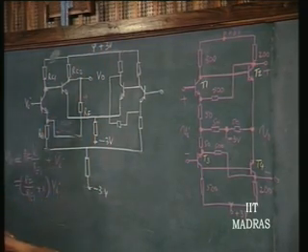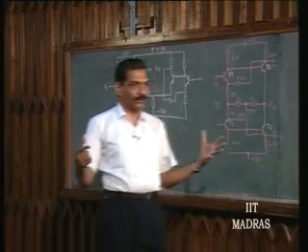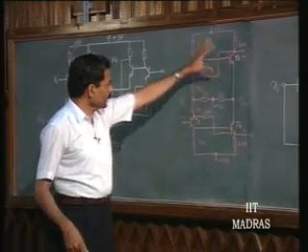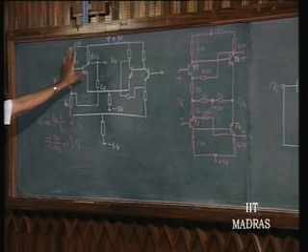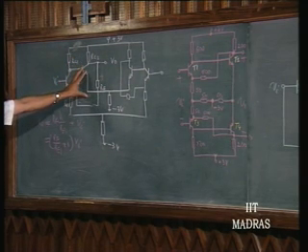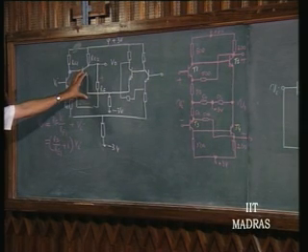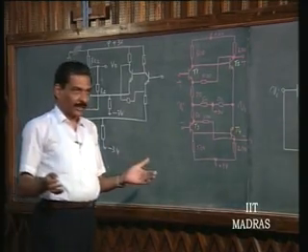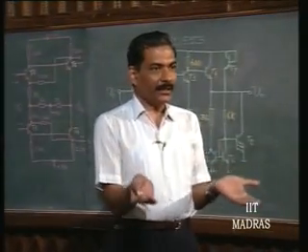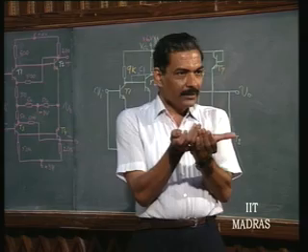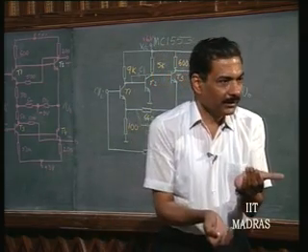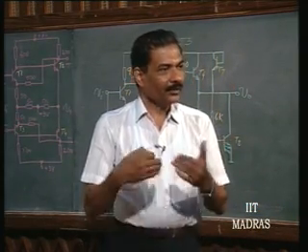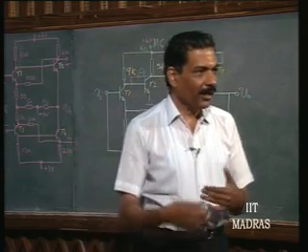See how simply the circuit gets transformed into an integrated circuit once you have the basic feedback configuration with you. So if you see this configuration, it is nothing but essentially this configuration. Do you follow this? How that can be synthesized simply by adopting the basic configuration and converting it to differential mode by simply lifting the ground to a common point where the common emitter resistance or the current source is connected. And the current source in turn can be connected to negative or ground depending upon whether it is dual supply or single supply.